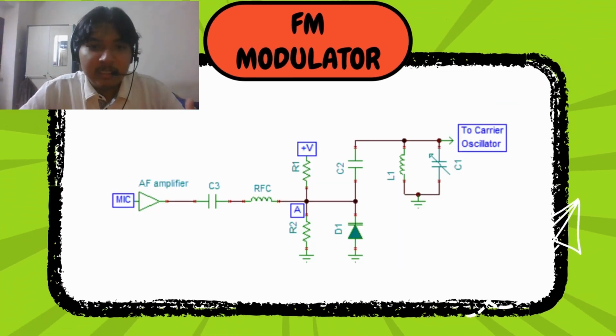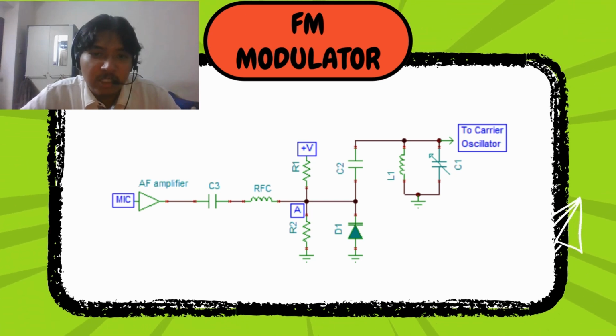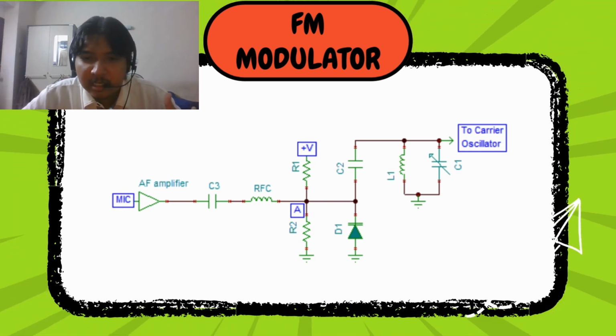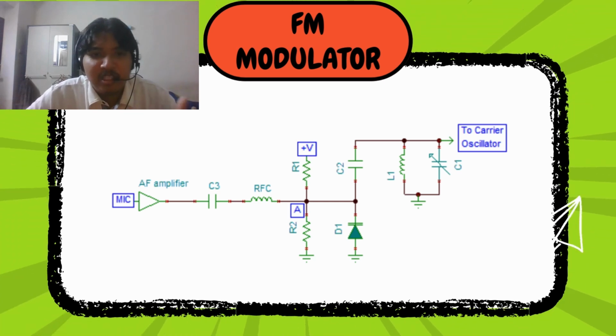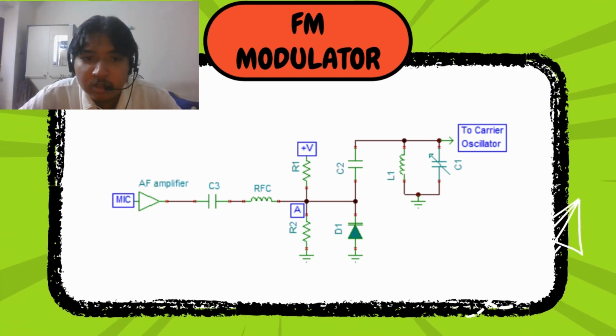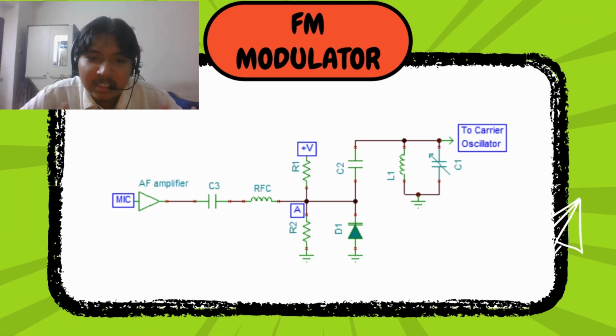For the FM modulator, it produces the frequency required for the carrier signal based on the message signal. We can use techniques such as voltage controlled oscillator or VCO. It is able to change the frequency in line with the message signal. So FM signal allows high fidelity audio to be transmitted using radio waves over a long distance. There are two types of designing VCO. You can use a varactor diode or reactance tube. In this case, this diagram here uses varactor diodes. A varactor diode is a capacitor.